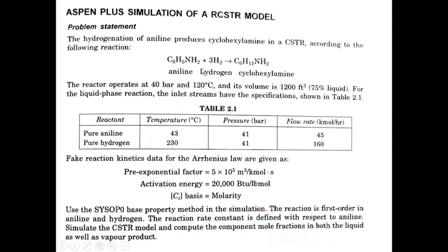Once you have specified all this, you have to specify the kinetics data, where the pre-exponential factor, activation energy, and the concentration term in molarity have to be specified. Once you specify all this, you are going to find that Aspen has said that the required input is complete, and then you have to simulate the problem.